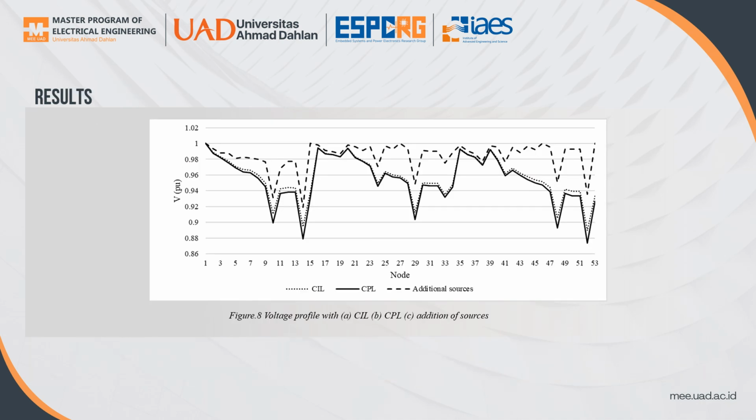The figure shows the voltage profile of all consumers. On the x-axis, we have different loads representing consumers. On the y-axis, we have the voltage profile, which is represented in per unit. In case 1, we have considered all to be only residential loads, which are constant impedance loads. As we can see in the figure, the standard voltage limit of 0.9 per unit has been crossed at 2 points as the distribution system is radial in structure.